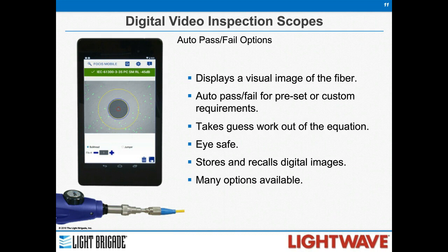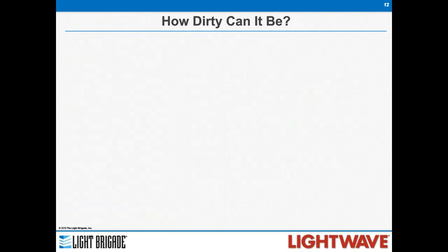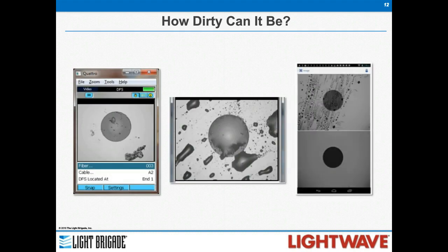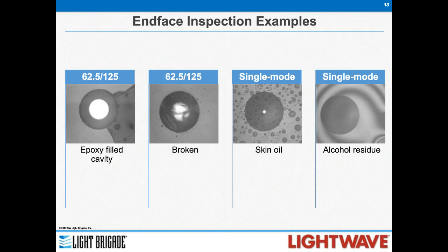Now, you've probably all seen this in one form or another. Dirty connectors: skin oils, dust, dirt from your tool bag, leaving it out, touching it with your fingers or palm can really damage or make the endface dirty. And that truly affects the performance of that connector mating. You also have damage. Once it's damaged, it has to be replaced. We don't make these up. I know we get them up on slides for display, but we see these in the field more often than you might think.